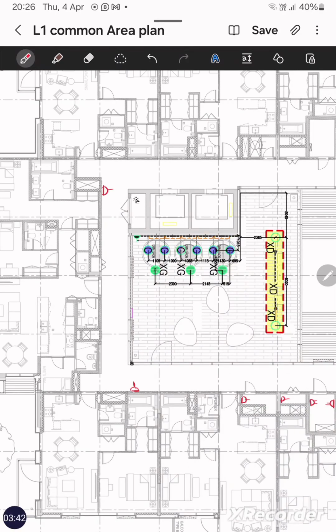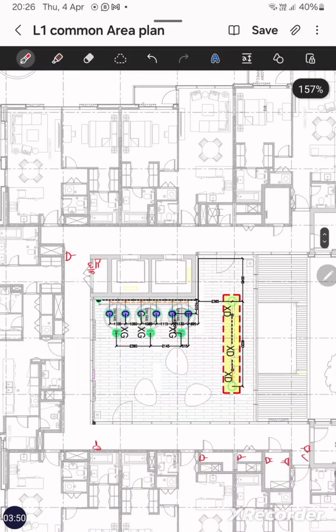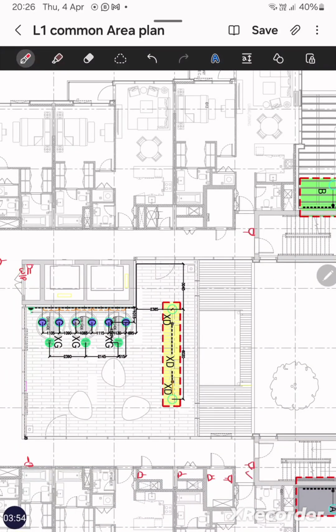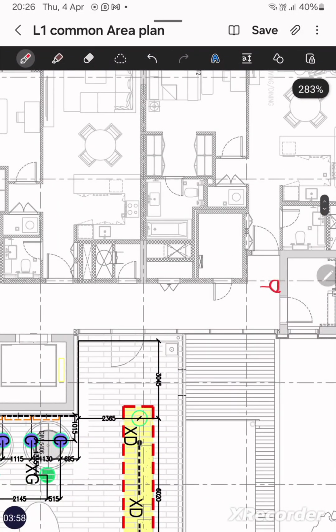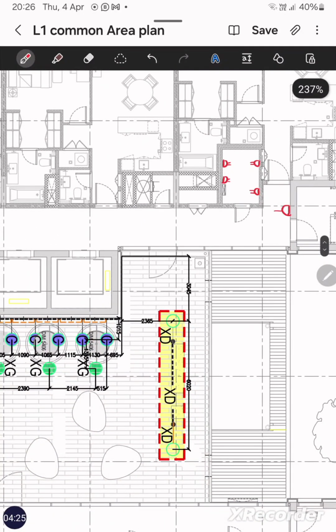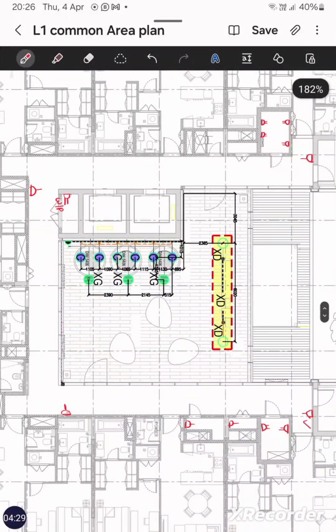In the water meter room, we need one double socket, but it will be weatherproof. Now we need one power socket here. This is the telephone room, so the requirement will be more in the telephone room. This will actually be reflected in the telephone room drawing, but we will consider the overall load for the telephone room, and the supplier will distribute that load according to their panel. So we will make 4 double sockets in the telephone room. Now we have completed the general purpose socket distribution in the corridor as well as in the services room.